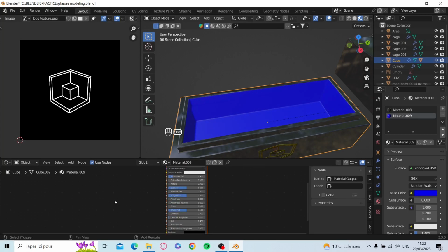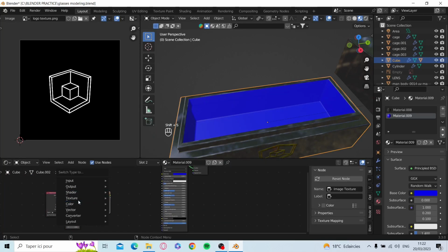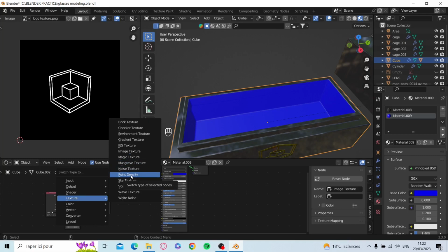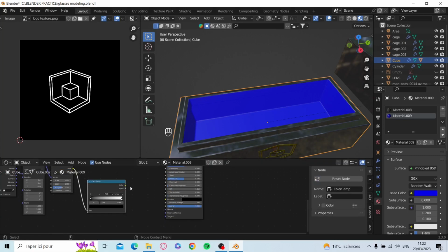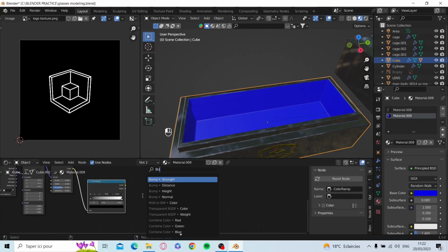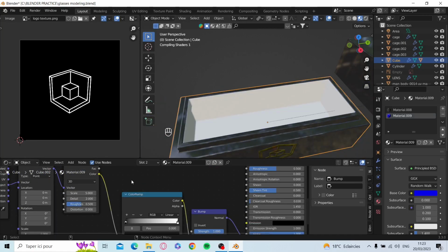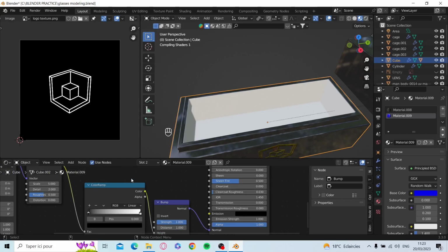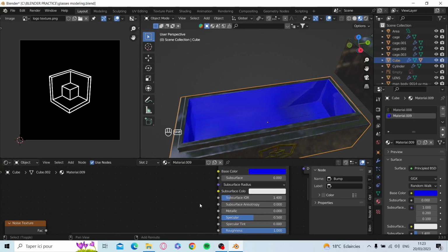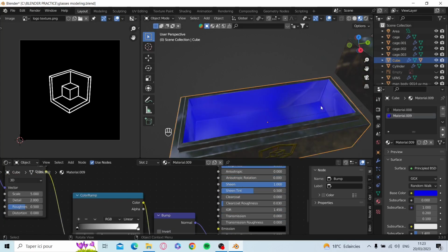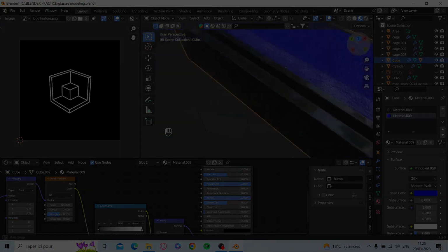And now, again, switch it into another noise texture or a Voronoi texture. They're not really that different. Plug the color into a ramp. It's pretty repetitive, but it gets the job done. Don't plug this into UV, make it an object, because we have not UV unwrapped this. Oh, another thing, make sure it's rough. Make sure it has a good sheen. So scale this down. And that's going to be it.